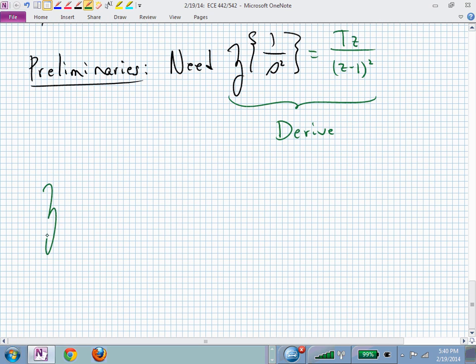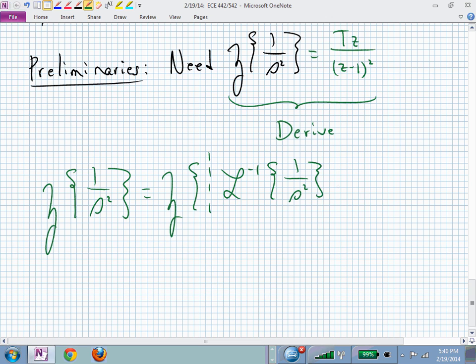So if we do this in a more lengthy manner, we're now starting with two poles at the origin, or a 1 over s squared, a pure mass system with our G of s, and reminding ourselves of what this z transform is. We sample the inverse Laplace transform of the 1 over s squared expression, and then z transform that sampled sequence of points.